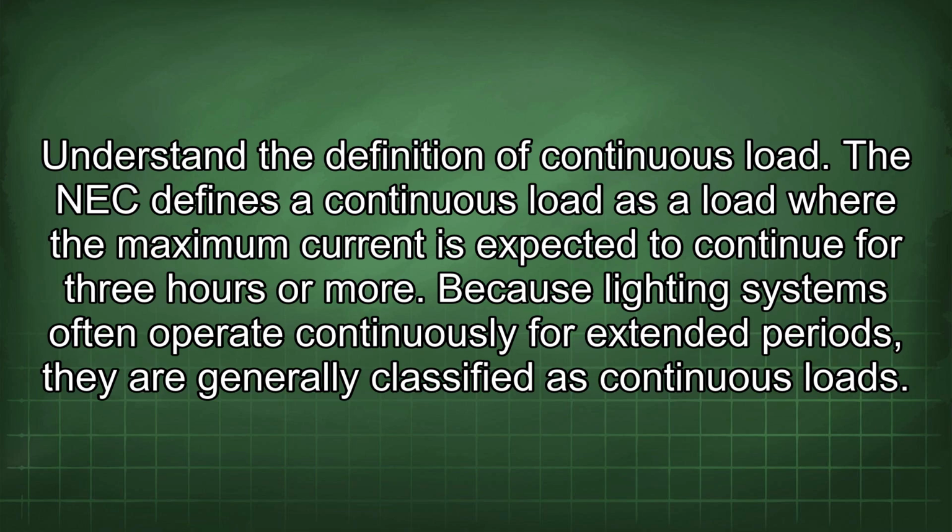The NEC defines a continuous load as a load where the maximum current is expected to continue for 3 hours or more. Because lighting systems often operate continuously for extended periods, they are generally classified as continuous loads.